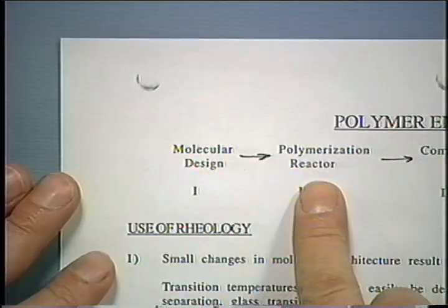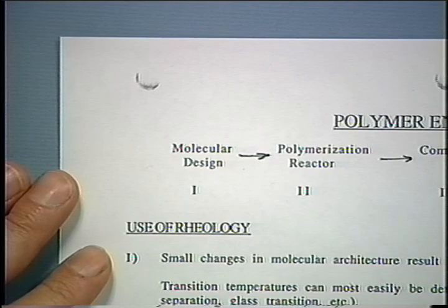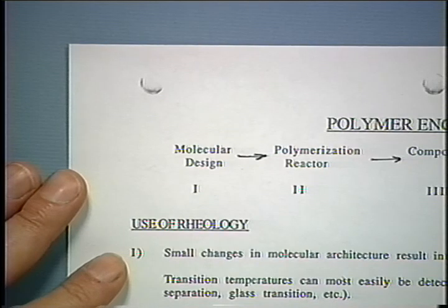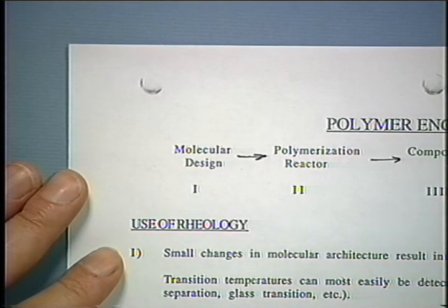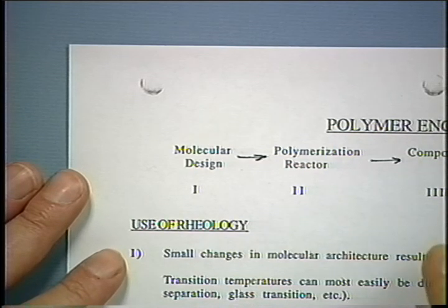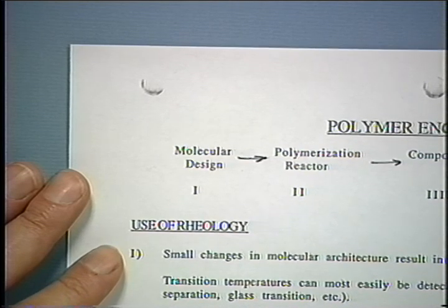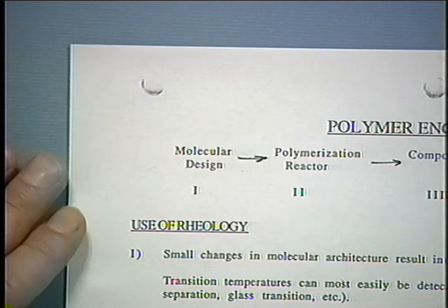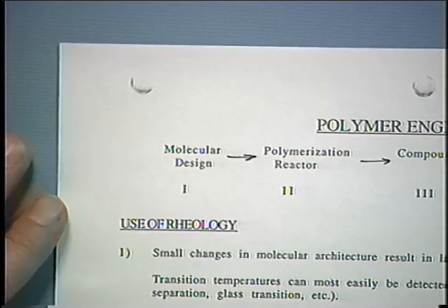The polymerization then and the compounding should be somehow in connection with rheology, because rheology would be a good sensor to see small changes in the molecule. When you might get higher molecular weight or more branching or less, or whatever, you have to coordinate that. One of the most sensitive indicators is maybe the relaxation time spectrum or the viscosity of the polymeric material, sometimes more sensitive than DSC or other physical techniques. So rheology as a sensor is very powerful.